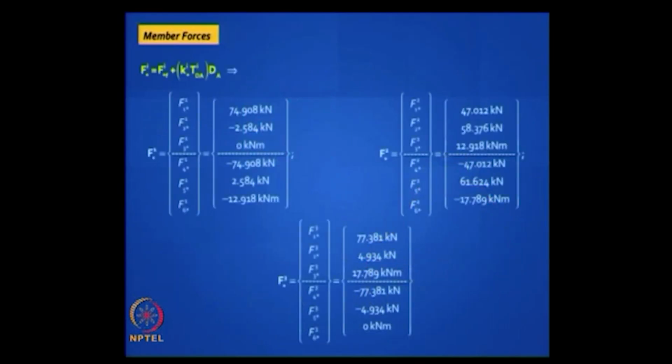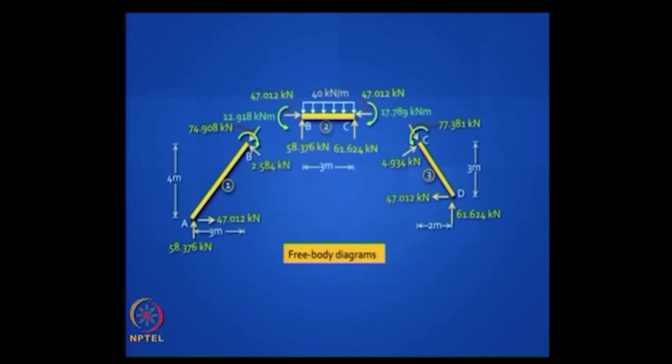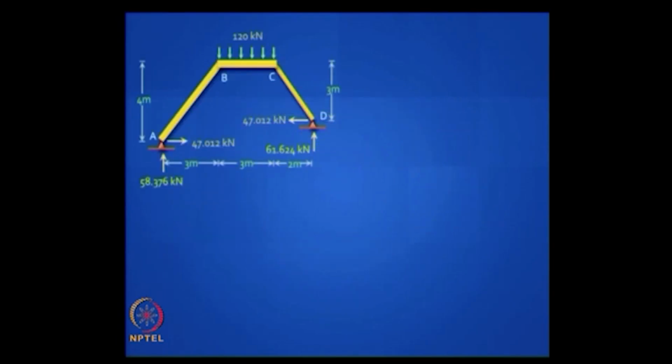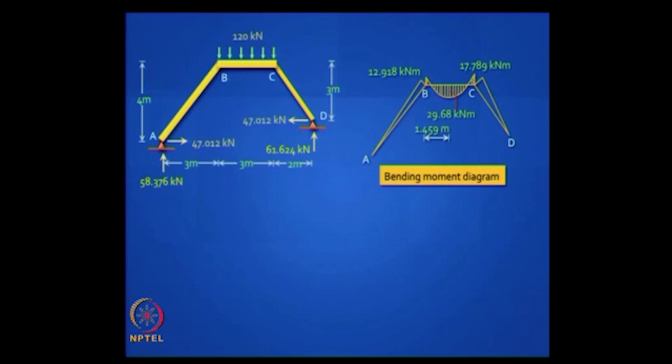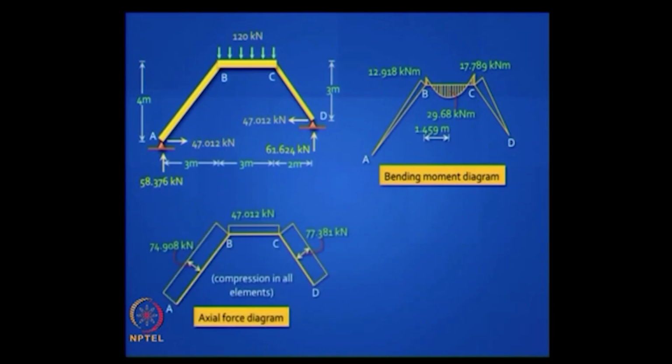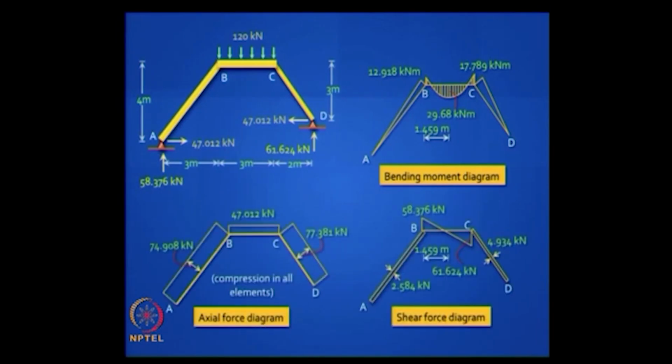Next, last step, find the member forces by using the TD matrix, and draw the free body diagrams, and draw the bending moment diagram, the axial force diagram and the shear force diagram. All this can be done, and compare these results with the results we got earlier by the slope deflection method,